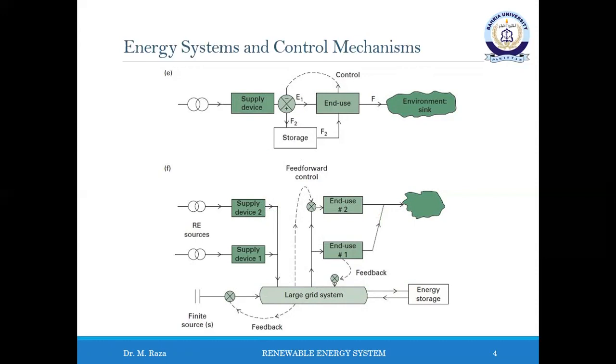The result is to decouple local supply from local demand by using the grid for both the export and import of energy. The grid becomes a virtual store. Moreover, there is still the benefit of having switchable load to optimize the on-site use of the microgeneration. This concept is shown in figure F.